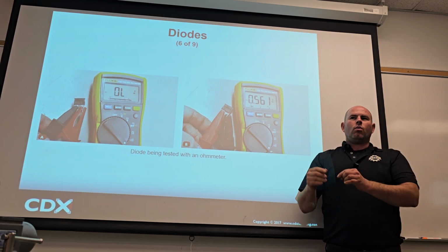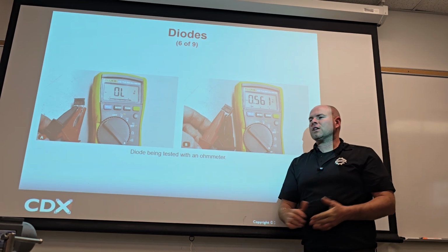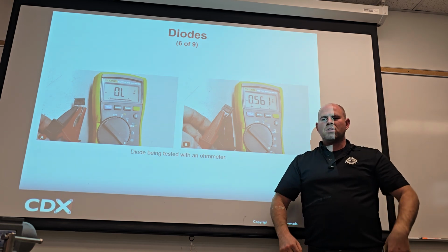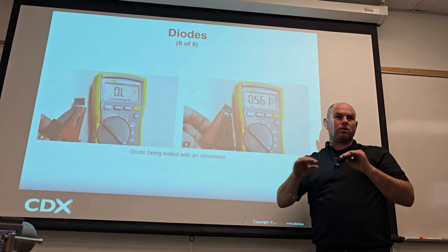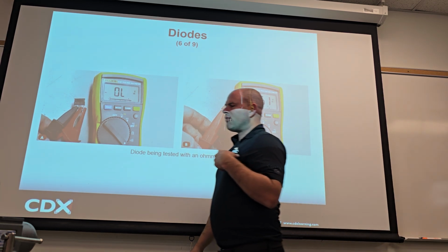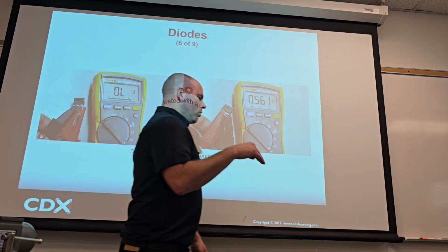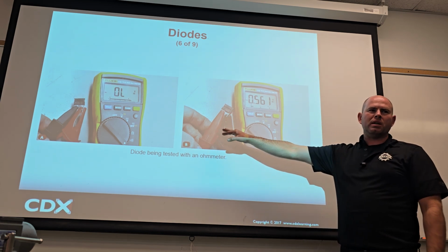Make sense? It's like the gospel truth. You have to reference it. You don't get to just say, well, that's a good diode or that's a bad diode. Unless you're really an expert specifically in diodes, you probably wouldn't know. I wouldn't know. The average technician wouldn't know. But at the end of the day, this is our job. Car comes in, car has a concern, AC blows warm. What are we selling the customer? And if the problem's a diode, then cool, but prove it to me.